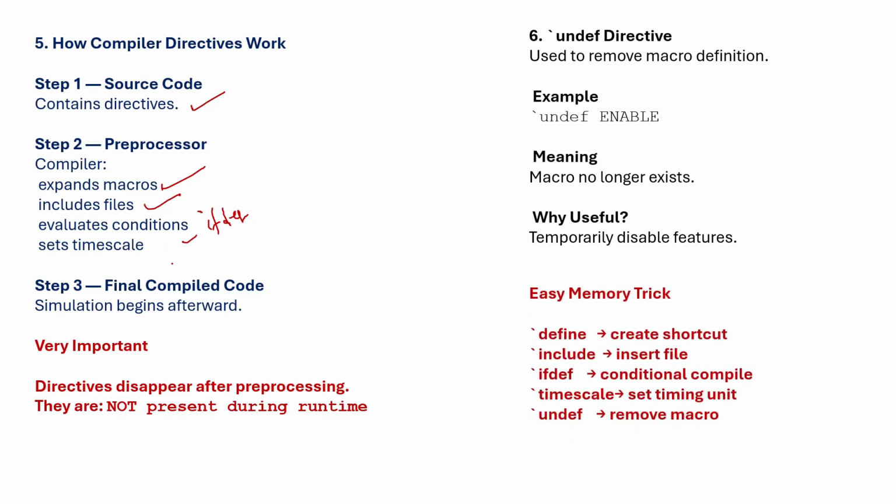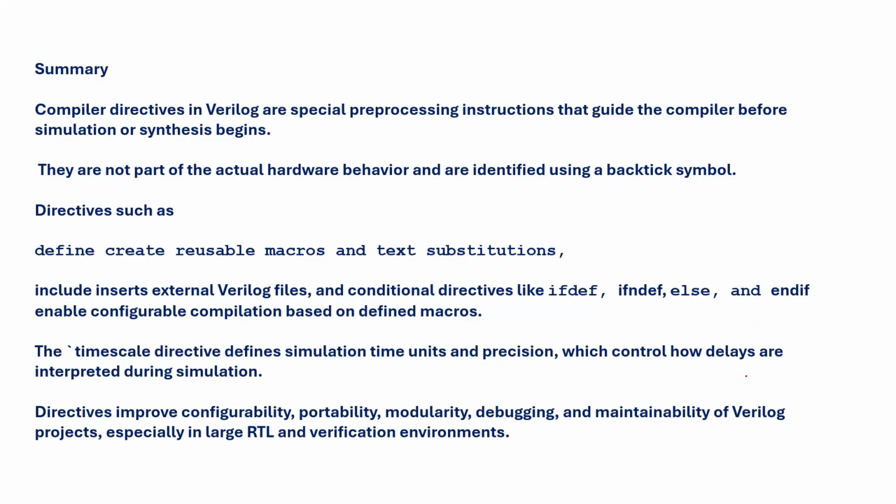Easily you can remember: tick define is a shortcut that will be replaced. Width and depth will be replaced with some shortcut names. Tick include inserts the file. Tick ifdef gives compilation conditionals. Tick timescale sets the time, and tick undef removes the macros. So this is what we explained related to compiler directives.